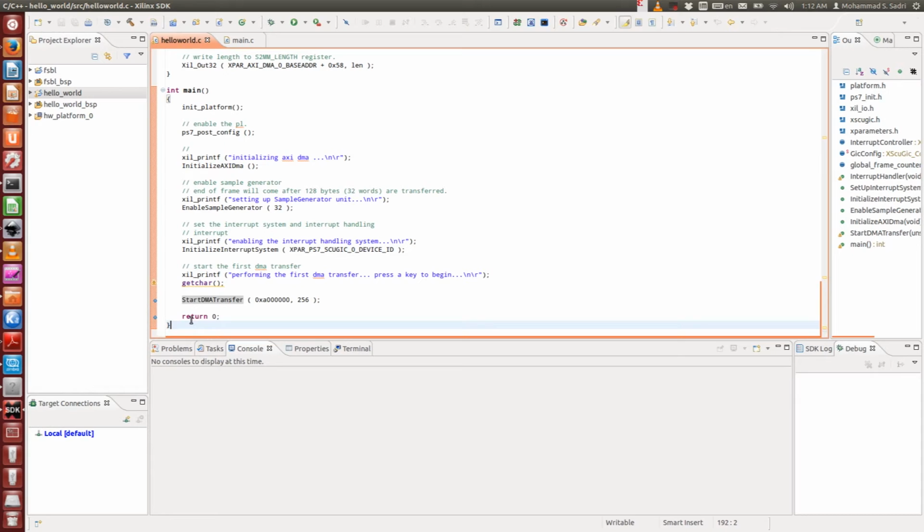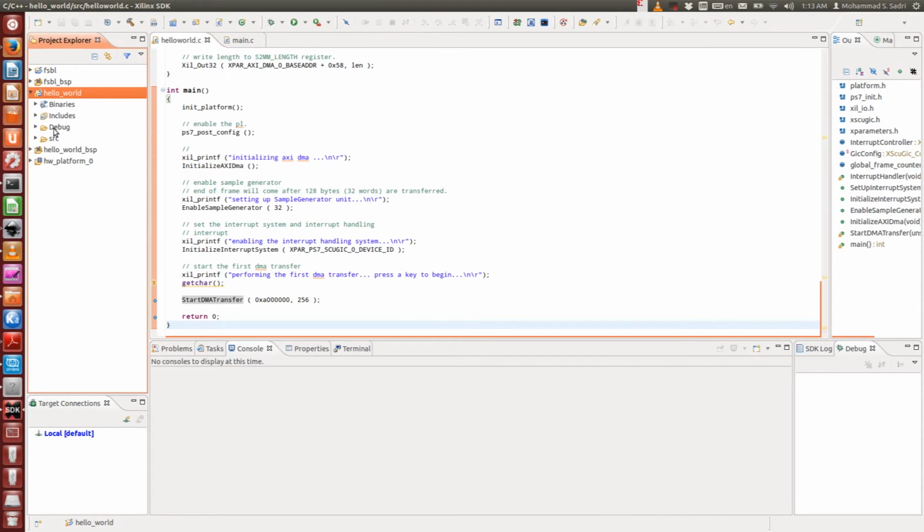Okay? And how do I see that? How can I analyze what the output of compilation is, practically the set of opcodes which are being executed on the ARM host of the ZYNQ? There are plenty of different solutions, but you can disassemble the ELF that is created for you. So I have written this code, it is compiled, and now I have this ELF file here, and you can disassemble this .elf file very easily.